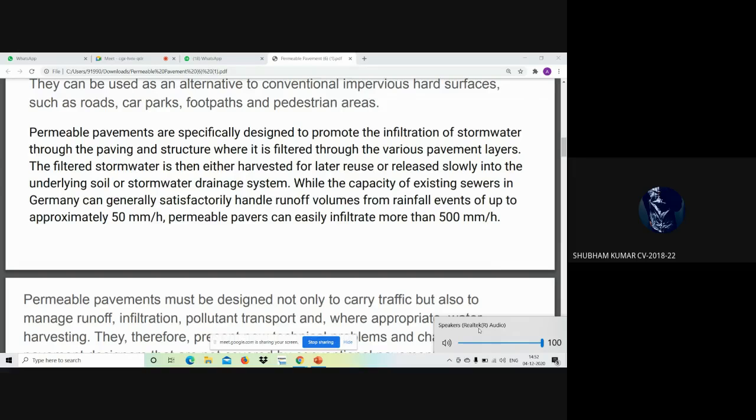In particular, the selection, specification, and characterization of material used in the surface, base, and sub-base of permeable pavement require designers to modify existing design methodology to facilitate water movement through the pavement, maintaining satisfactory serviceability under traffic in saturated condition, and to provide adequate water storage where required.